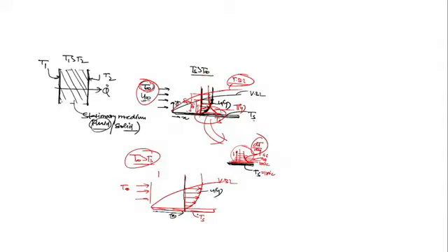Now how is the temperature going to vary? Obviously at the surface, at y equal to 0, temperature is less. It's Ts here. Any fluid layer on the surface will be in equilibrium with the surface, that is Ts. And as we are moving upward, temperature changes. Temperature increases, yes or no? And then it reaches T infinity. I am not going to write an arrow here. It's a simple profile. This is Ts, and this is T as a function of y. Temperature increases, and when it reaches T infinity, this is called the thermal boundary layer thickness. Is this clear?